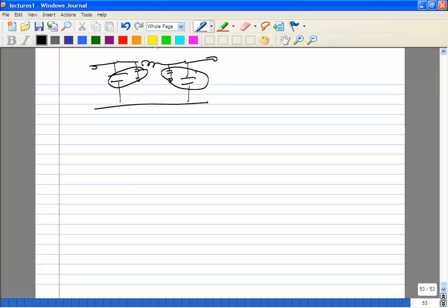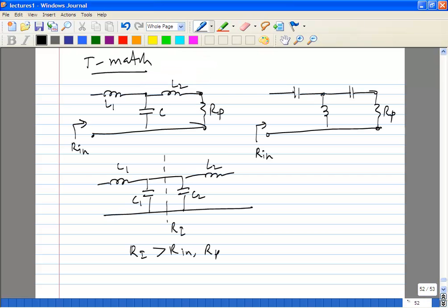And of course, the other advantage is the matching network will not be sensitive, because you have a large capacitance in parallel with the parasitics. It won't be very sensitive to the parasitics of the inductor. Similarly, for this one, you have this parasitic coming in parallel with C, so you may end up preferring this one over this one in some cases. So it all depends on what is the value of the inductance, how much parasitic capacitance it has in parallel, and how much area you can afford. You'll have to trade off all these things when you are designing your circuit. Okay, is that clear?